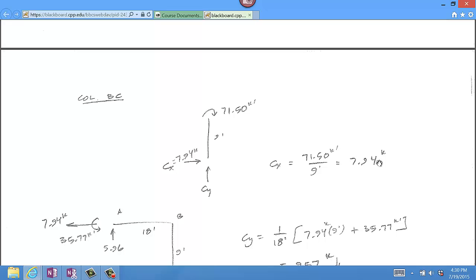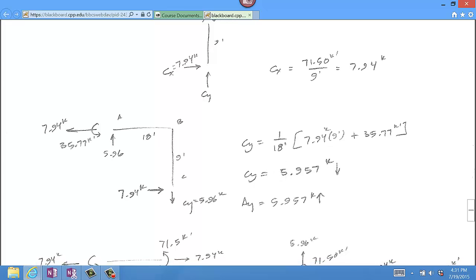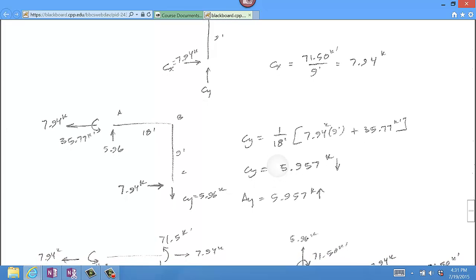So it takes almost 8,000 pounds of force to pull the column from the original vertical to the current location of the anchor bolts. And so the 1.2 inches of offset, in order to make that dimension up, will require almost 8,000 pounds. And so I have a complete free body diagram here to calculate the remaining reactions, AY and CY.